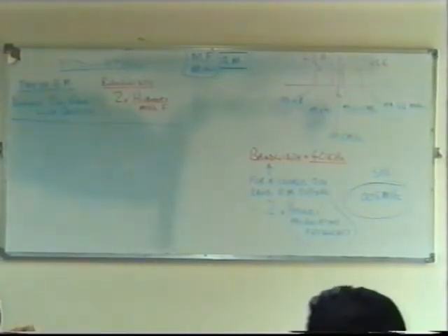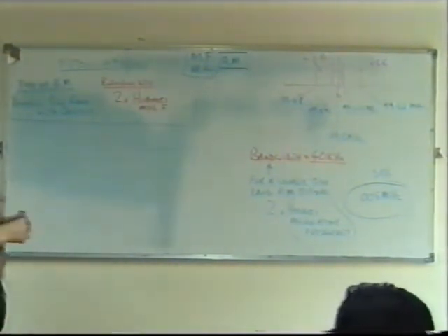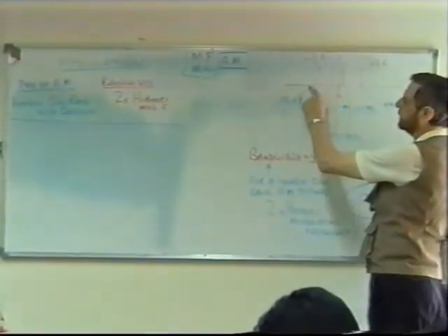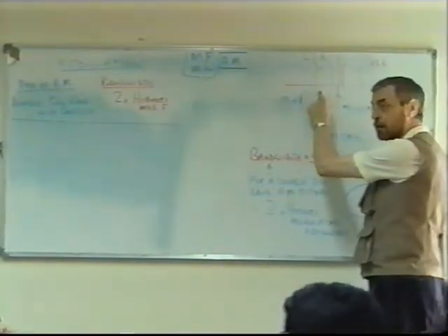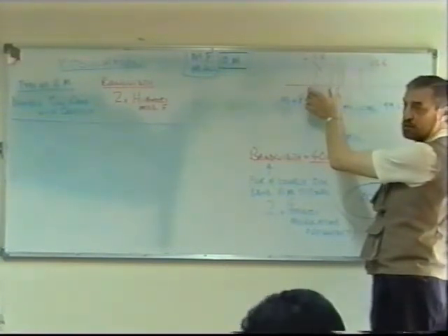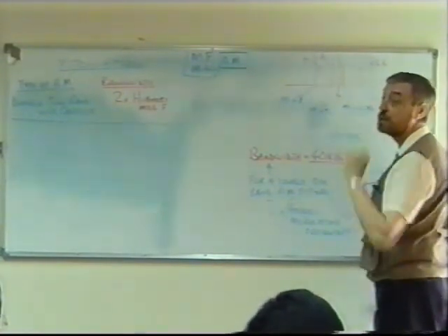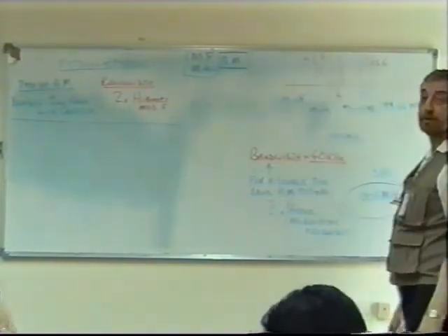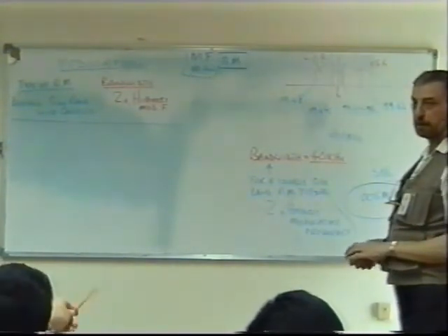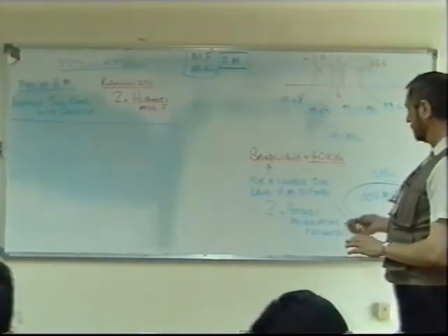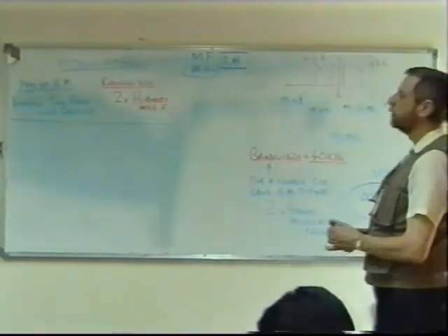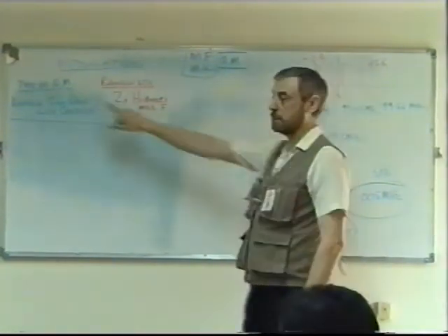For the lower sideband, the bandwidth will be 15. What you've got to do to find the bandwidth of a lower sideband by itself, we'll be talking about that in a minute, is really the difference between the highest and lowest modulating frequency, which would be 15 kilohertz in that example. But we'll talk about that in a minute. For double sideband, this is the same as this, exactly. What I've described here is this.